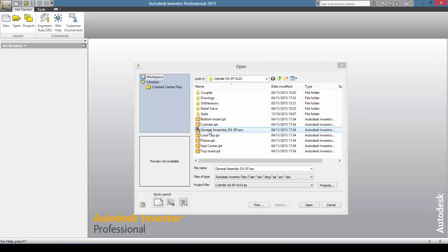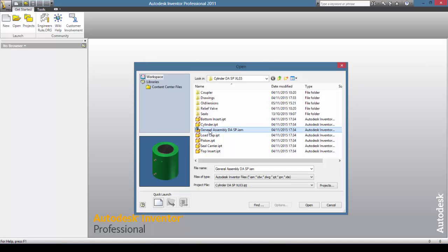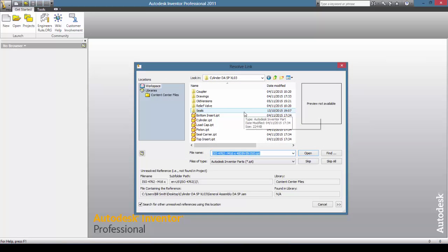This video explains the management of Inventor Contents Center components imported from other systems, or migrated to newer versions of Inventor. The focus being the unresolved Contents Center components. When opening a project assembly file, some files may be unresolved, with the result that some components are missing.